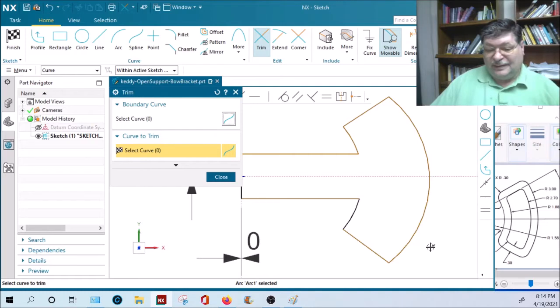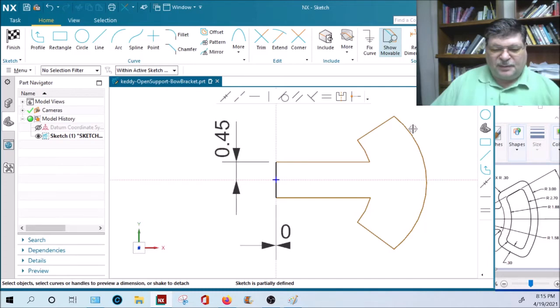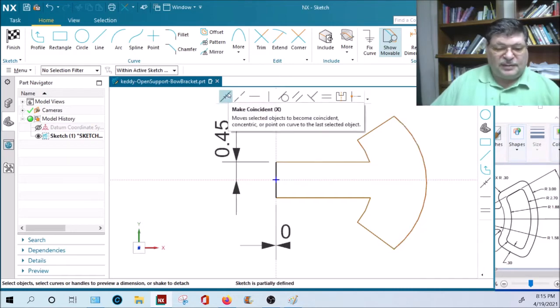Okay, let's see if we can get this thing centered or correct. Okay, let's find out where these arc centers are. Let me close this. When I put the cursor on an arc, it gives me a little point so you can see where the centers are. Now they should be on top of one another. So I'm going to go up to here and say concentric.